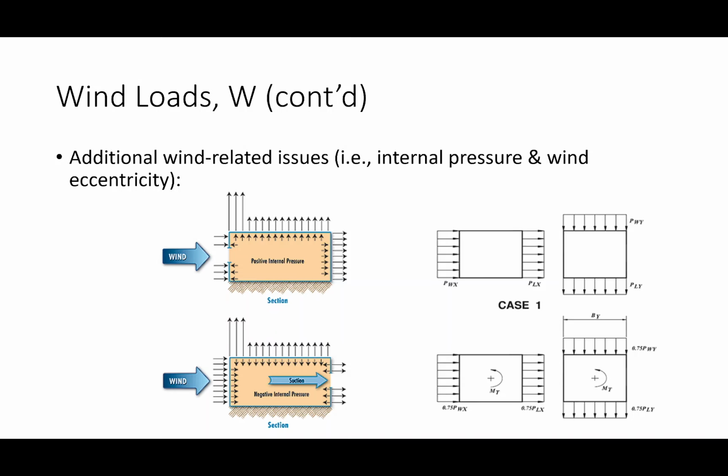The first thing that I'm not talking about is gusts and changes in internal versus external pressure. How many of you have ever been in a building like this on a really windy day and found that the doors have a tendency to want to stay open? Whenever wind hits a building, not only do you generate pressures outside the building, but you generate pressures inside the building as well. So that pressure that we just calculated, you would ultimately adjust for not only gust effects, but changes in internal versus external pressure.